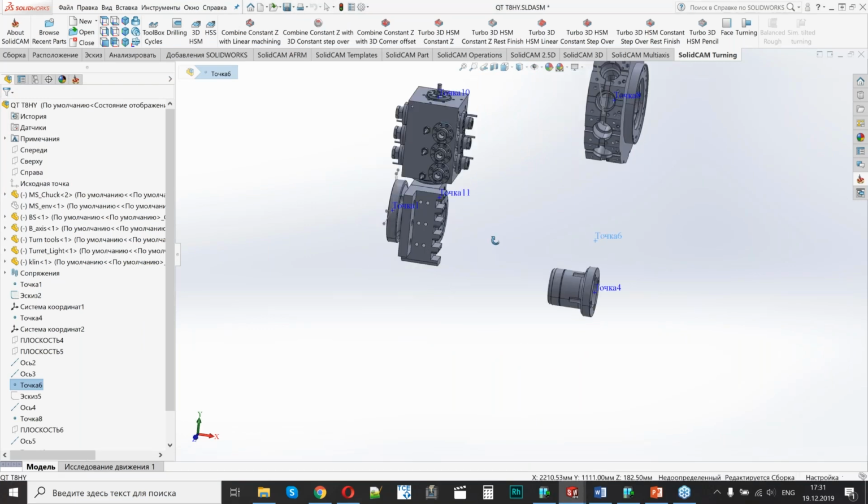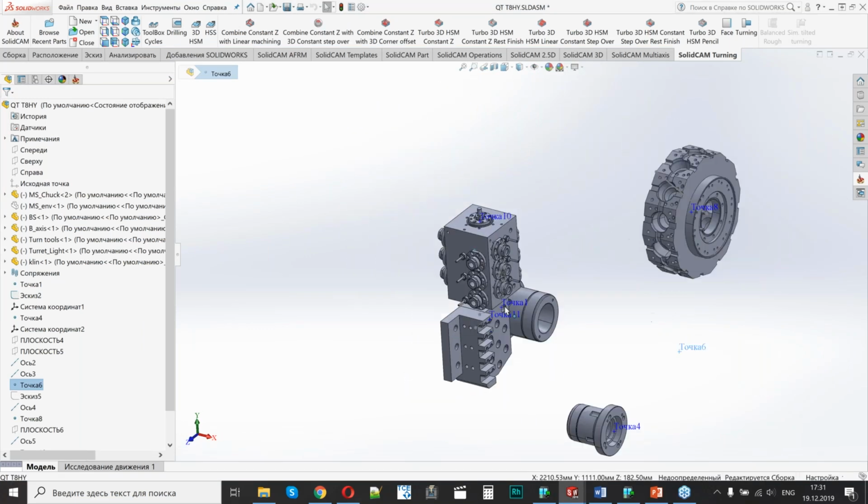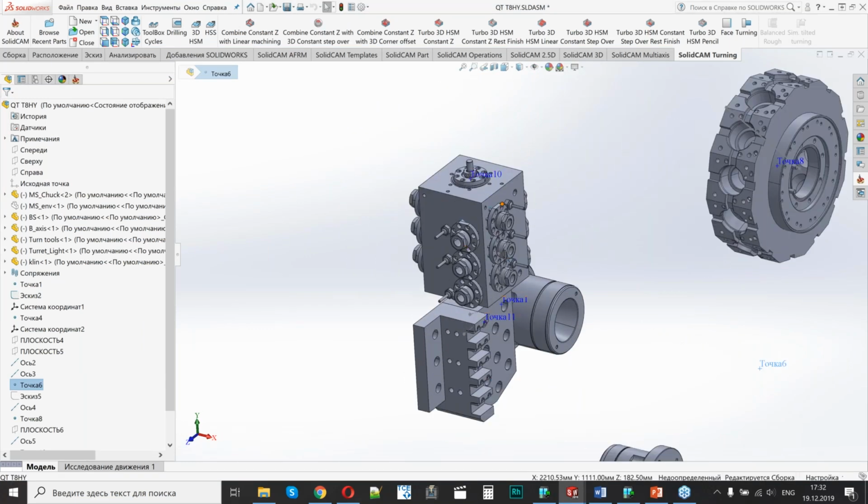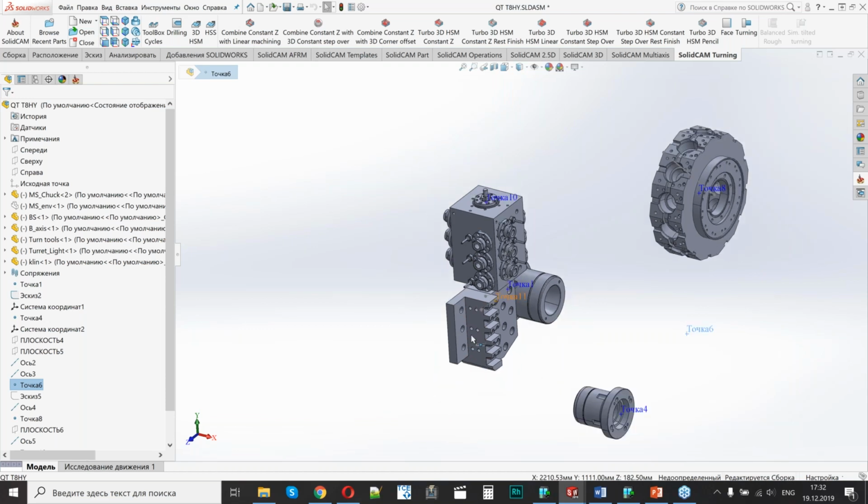So what do we know about the tool post? It has a B-axis here, but it can also move in the Y-axis. The Y-axis for the second channel is the same as the X-axis for the first channel. So it moves up and down. That's all it can do.